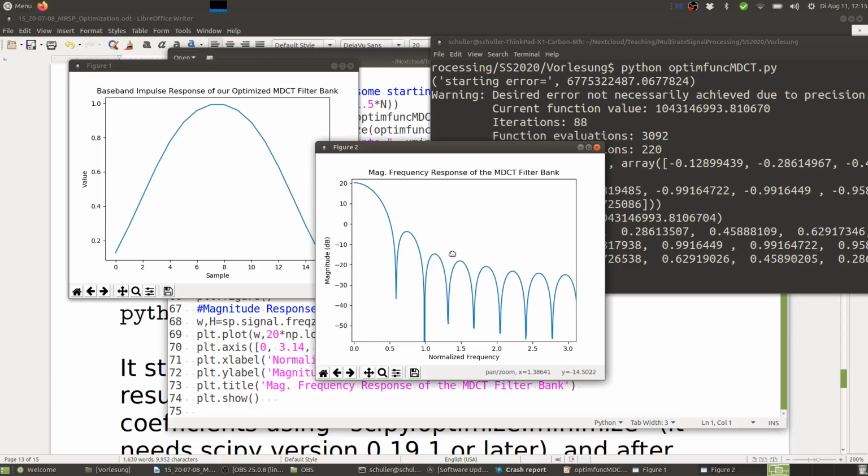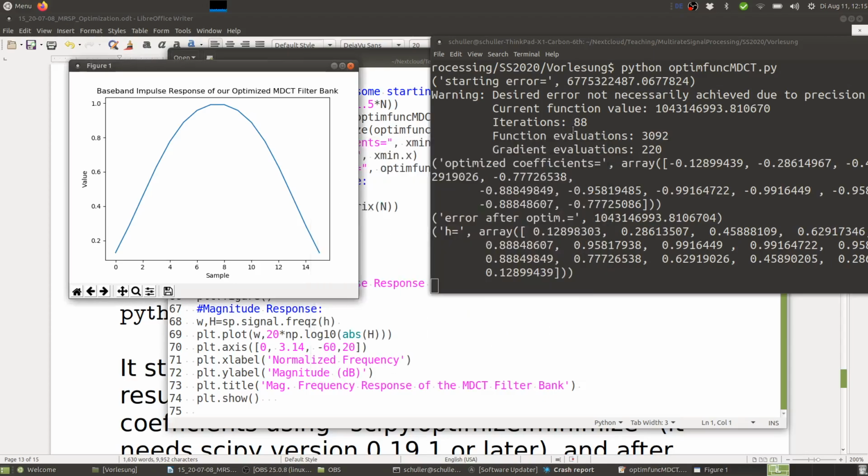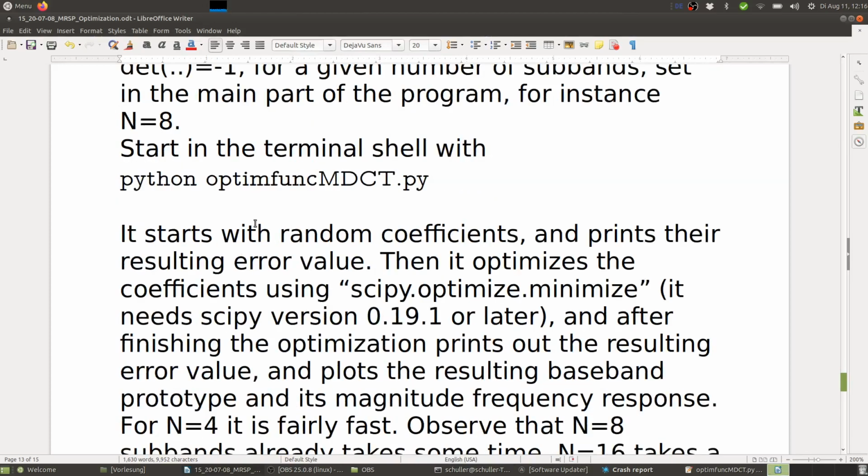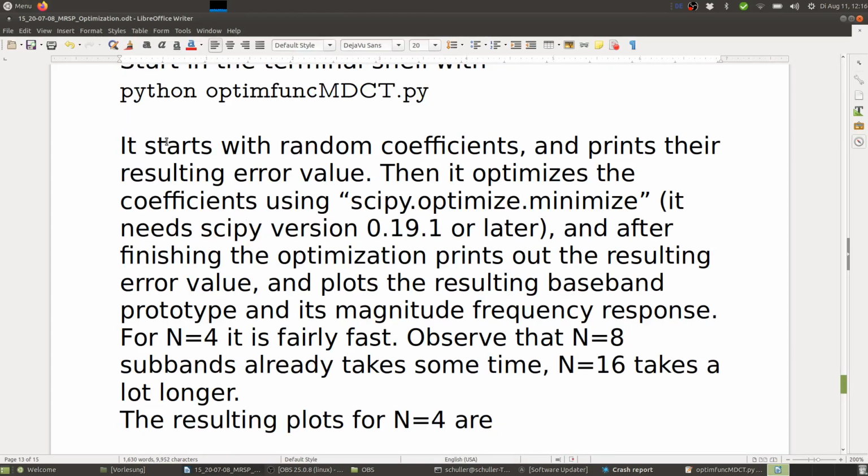and this is because basically this first side lobe here is still part of, at least partially part of the transition band, and then here we have the stop band, and the stop band has the same weights everywhere. So that's why the ripple height now became more similar than in the non-optimized sine window case. So here we get about -20, so we have about -40 dB stop attenuation. Not great, but it's kind of okay. Yeah, so this in principle is how it works. So if you want to have more attenuation, for instance, you could choose the transition band wider.